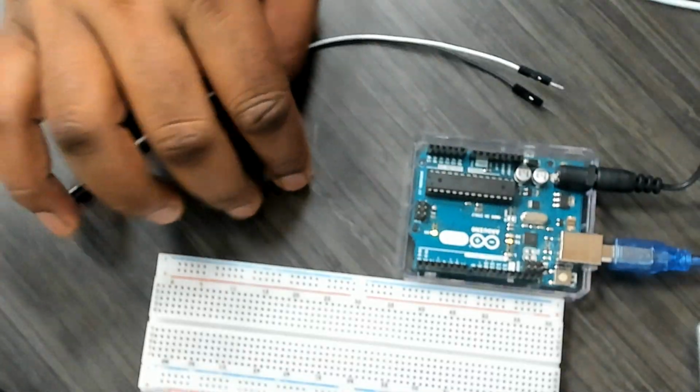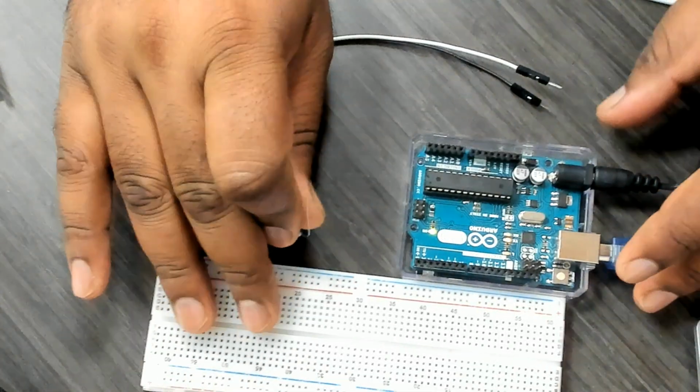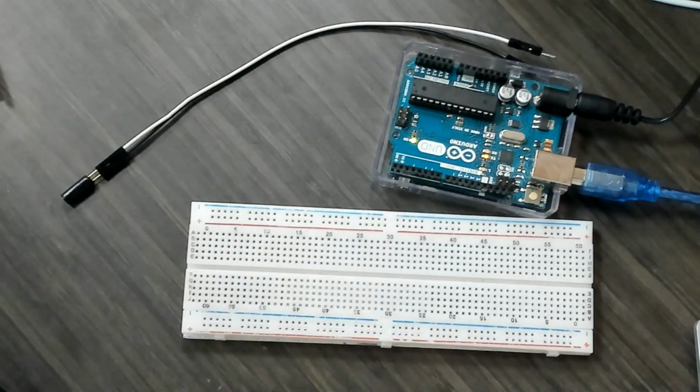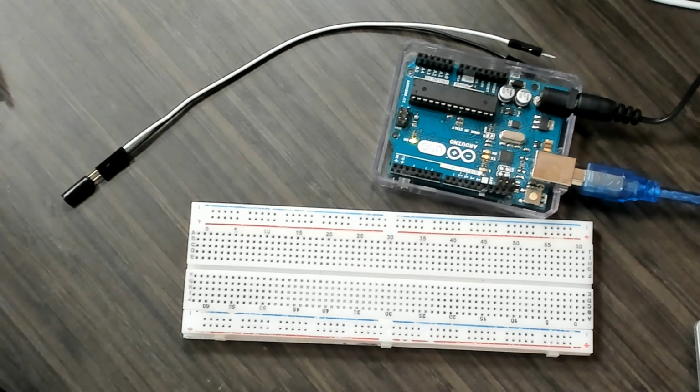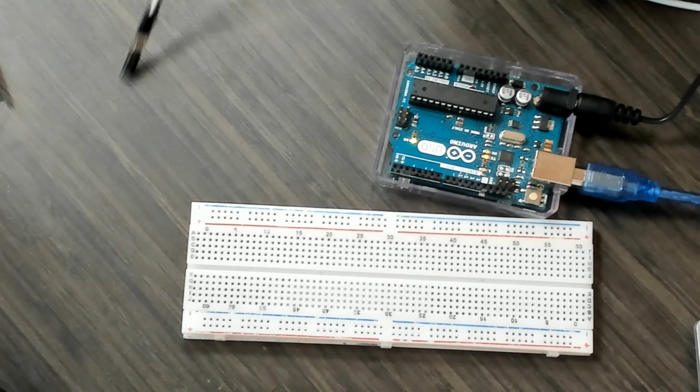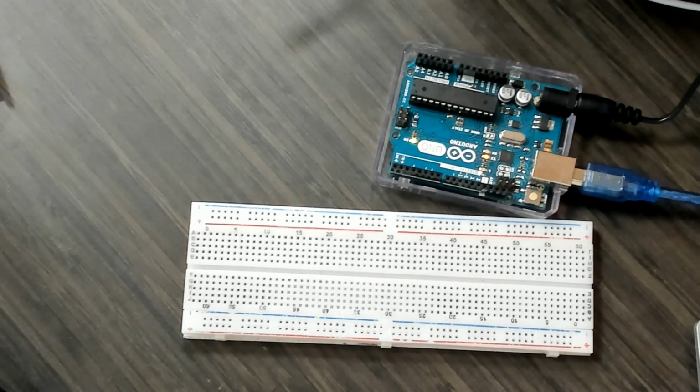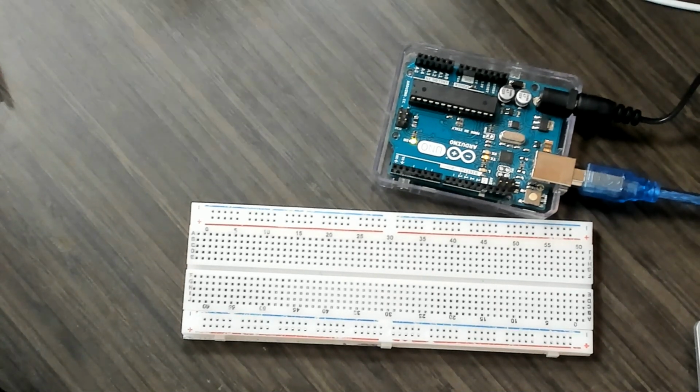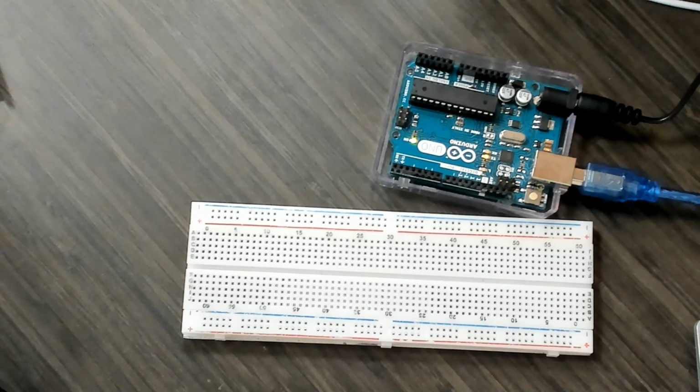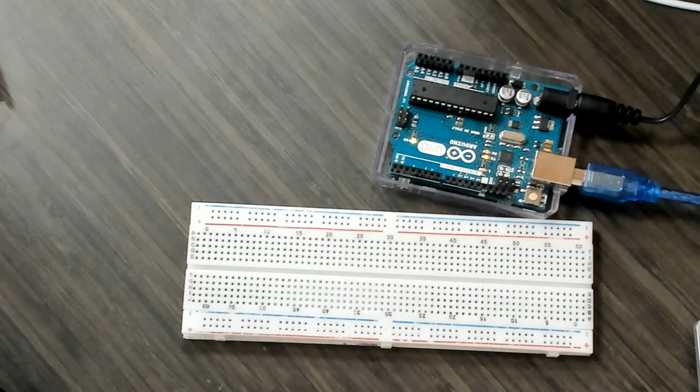We didn't talk about something called a pull-up or a pull-down resistor in the previous modules. A resistor serves another purpose. In a condition like this, we are going to program and read a digital pin, and if it is high, then we'll do something, like turn on an LED, and if it is low, turn off an LED. We have done programs like that before.